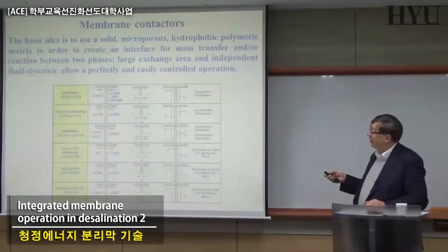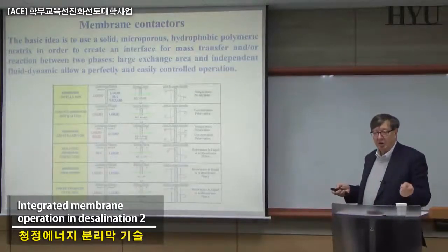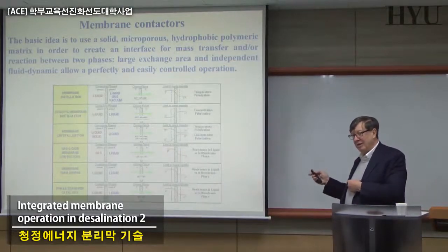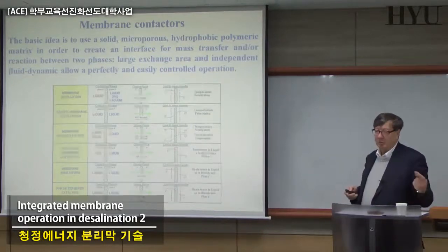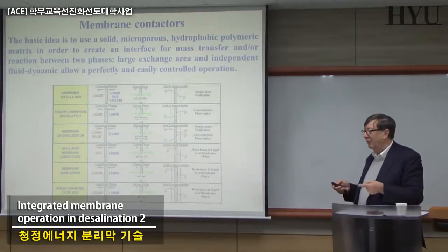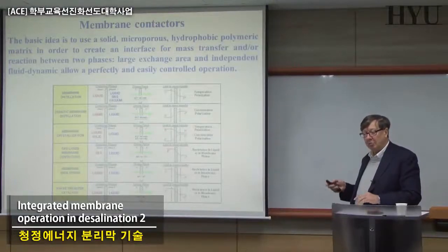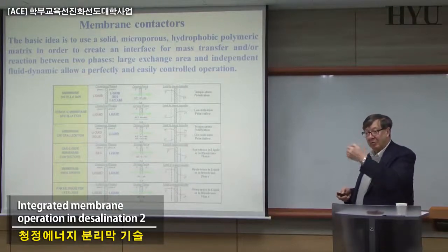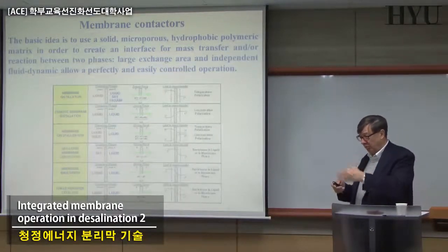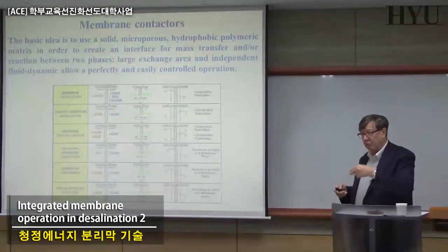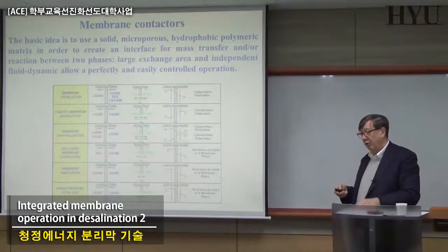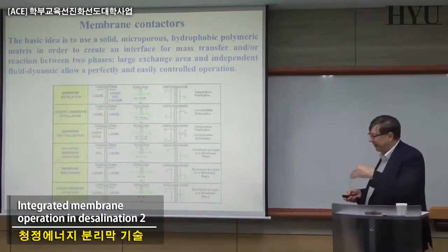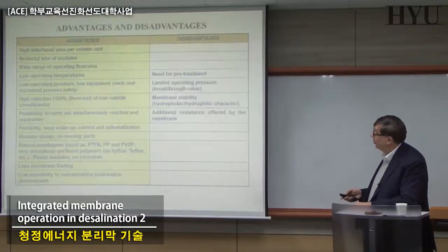In some cases, some of these technologies are competing with nanofiltration. One of the motivations for the interesting behavior of membrane distillation, compared to nanofiltration, is that the level of traditional fouling in MD is much lower than in NF, because we don't have a convective flux normal to the membrane surface, so species don't accumulate. It's much easier to keep control using appropriate cross-flow velocity, etc., which for industrial application is quite interesting. There are different of these things that can be important.